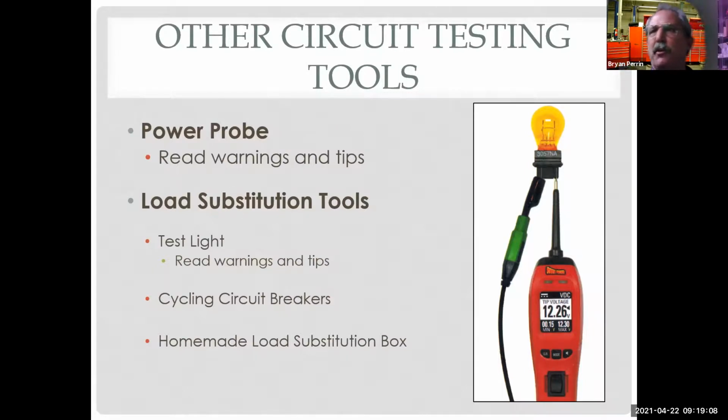So this is a portable power supply that's connected to the battery that gives me a 20-foot cable. If you buy the bigger kit, it comes with a spare 20-foot cable. So if I'm working on my truck with the trailer on it, I can go all the way back and check my trailer lights. I'm still connected to the main battery. So I can see, do I have a bad ground in the trailer? I can troubleshoot the whole thing very efficiently. This is what's replaced test lights. So I use this much more than a digital multimeter, although it doesn't do all the same functions. It's a voltmeter.